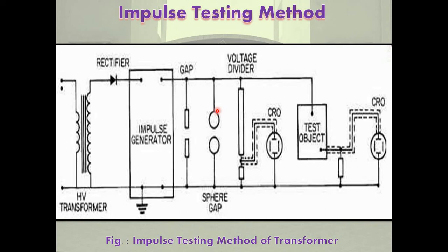Once the voltmeter is calibrated, the voltage of the LT side can be measured by the voltmeter, and the HT side voltage can be obtained by multiplying with the turns ratio. In this method, a capacitor potential divider or resistance divider is connected across the HT winding of the high voltage transformer. The potential divider consists of several air capacitors in series. The voltage across one capacitor is a definite function of the total voltage. The smaller voltage is measured by means of an electrostatic voltmeter.